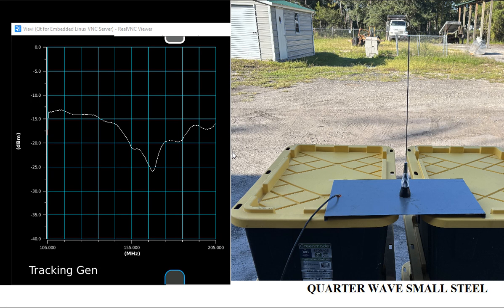which is what happens when you have not enough ground plane. And I'm using a little chunk of steel here, and it's nowhere near long enough as far as being able to lay this quarter wave down and rotate it around. So it's ground plane deficient. And what this ends up doing is it changes its center frequency by a lot. And in order to pull this back, you would need to increase the whip length.